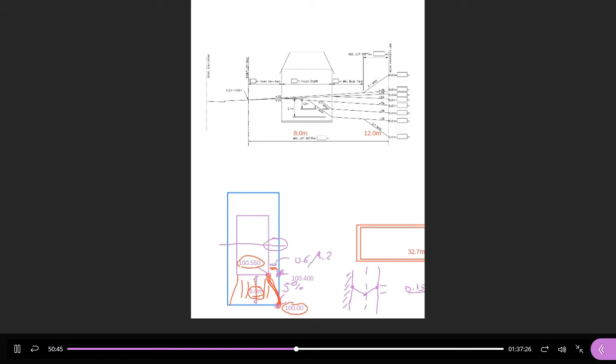So if the architect wants to use maximum 5%, I have to use something flatter to get the elevation opposite the corner of the house along the side of the lot. So let's reverse engineer it. What if we go from 100 up to the house at 5%? So instead of using 55, I'm going to use 0.4 over here. 100.400. That's 5% up from the corner of the lot at the front to the corner of the house.